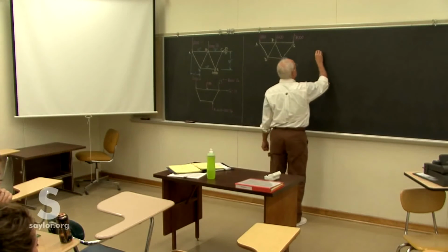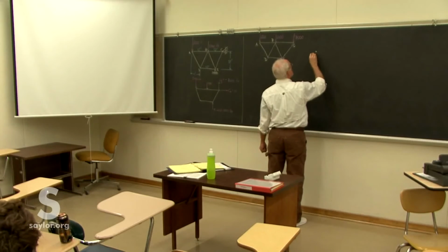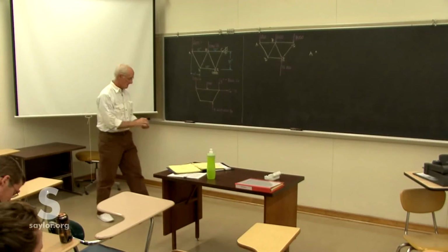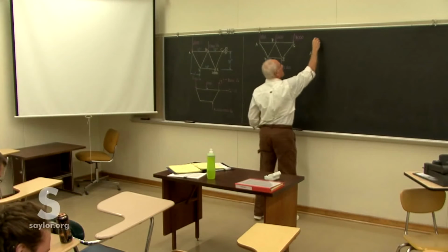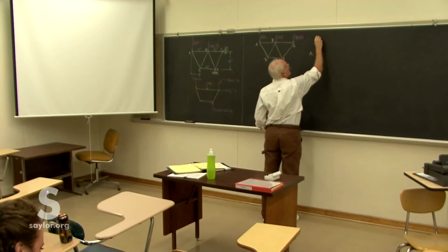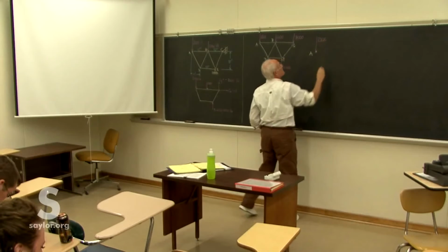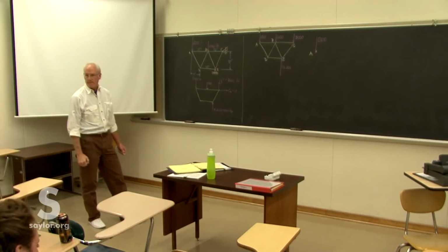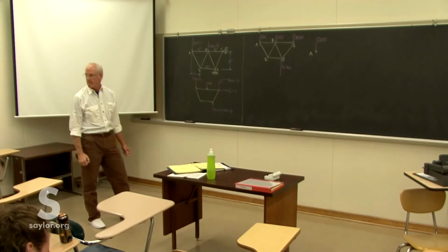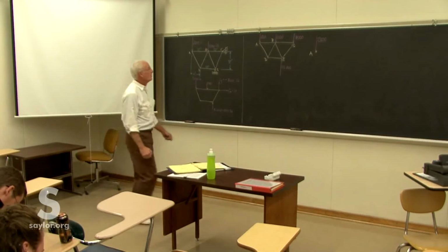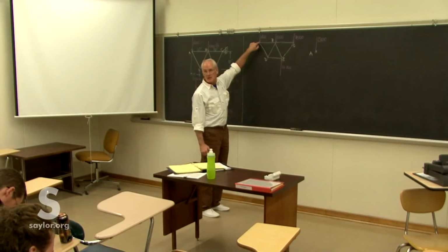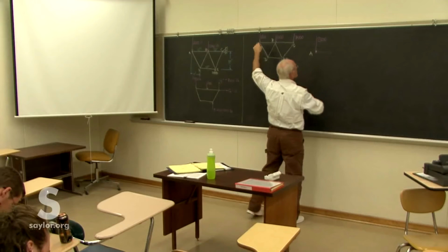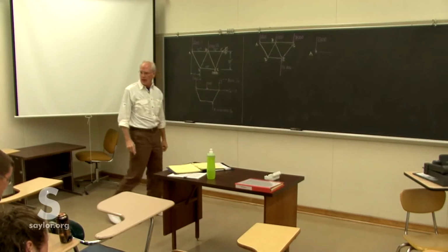So we'll start at A, just because it's nearest to the drawing as I start putting these in. I know it's got the 2,000-pound load. I know there must be a force coming from the member that connects it to B. So I'll just draw that line. I won't put the arrowhead on yet.